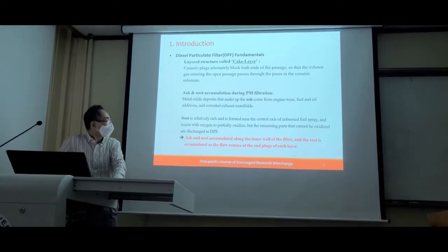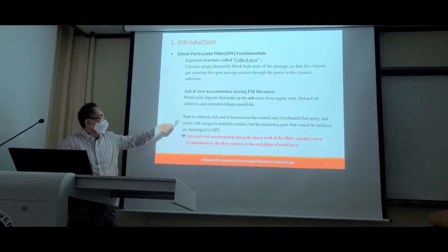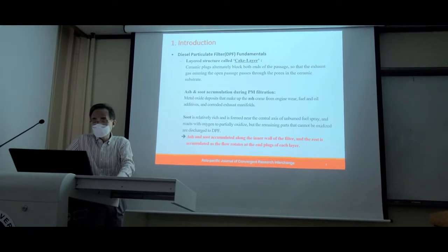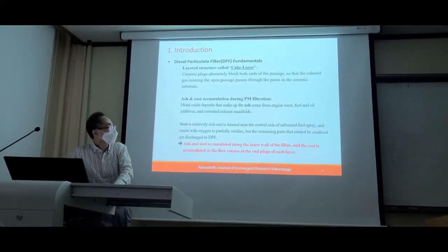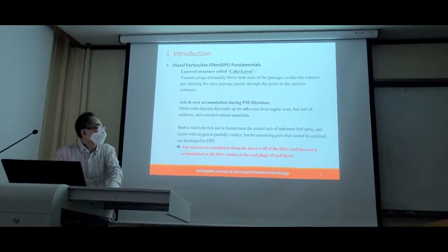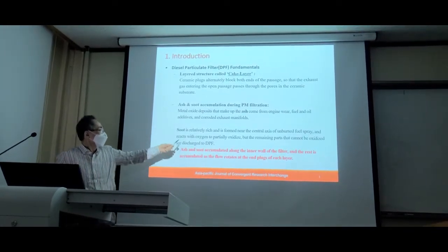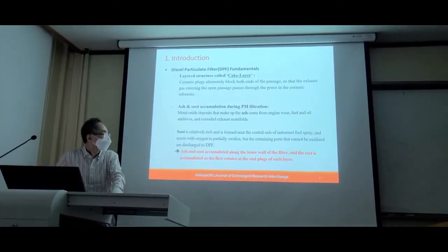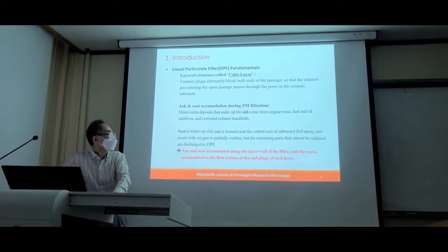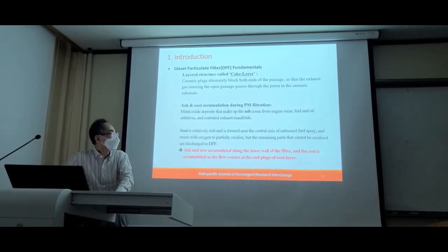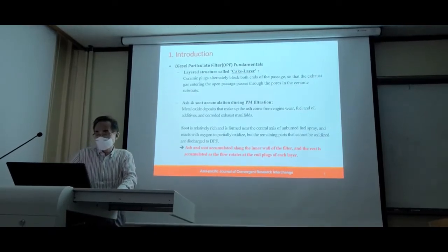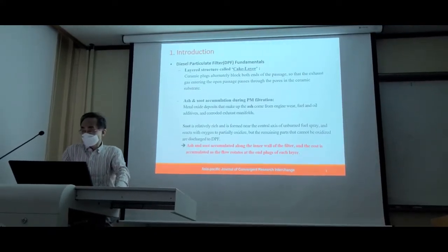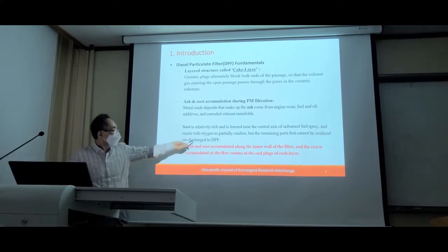And another thing which we have to be very cautious about is the soot. Soot is relatively rich and formed near the central edges of unburned fuel spray, and reacts with oxygen to partially oxidize, but the remaining parts are discharged to DPF.